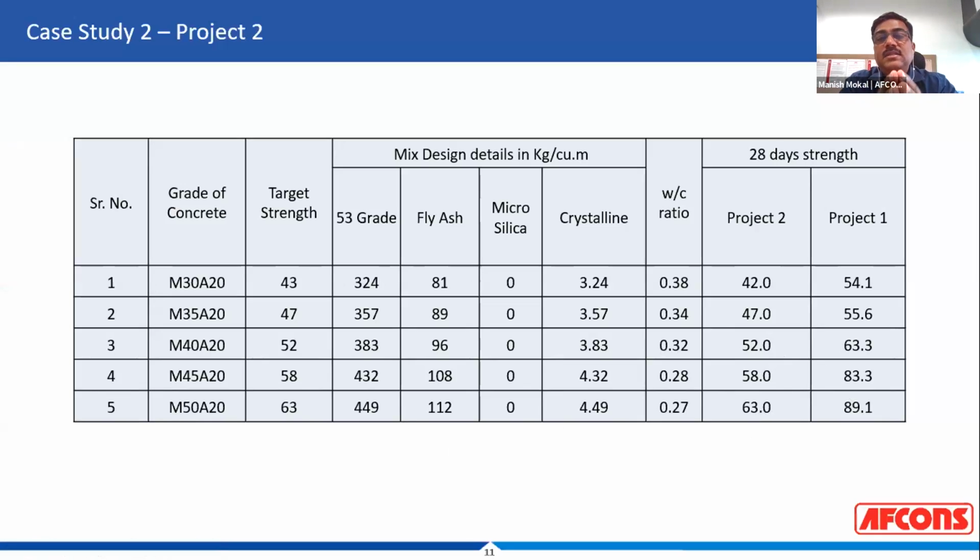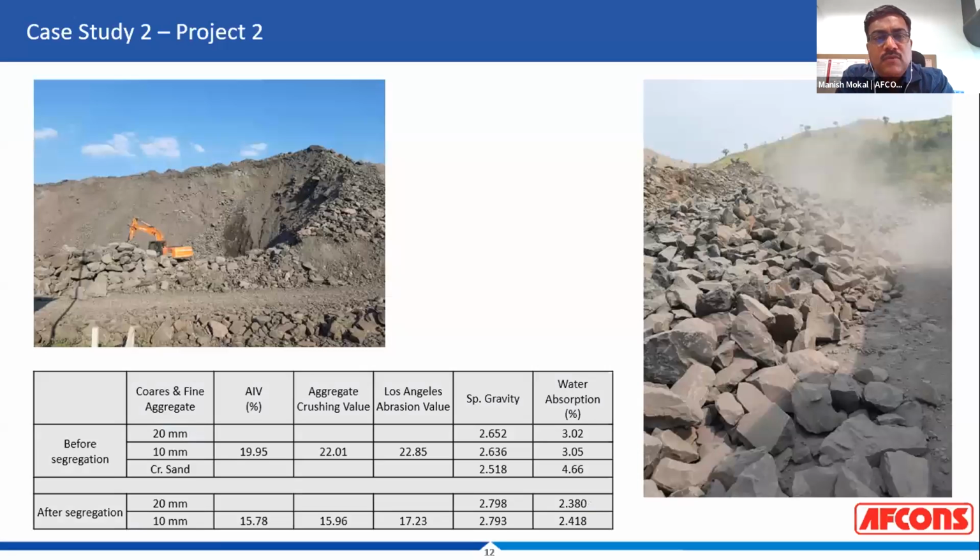However, the idea is, in and around your area, look at not just the closest and the cheapest, but multiple options, look at a better quality and do a proper cost benefit analysis and see whether it makes sense. So then what we did was we started manually, physically segregating the poor quality rock that we were getting and then crushing the remaining part of the rock so that we could get a better performance from the aggregate and we could lower our cement contents and do a better and a more economical job.